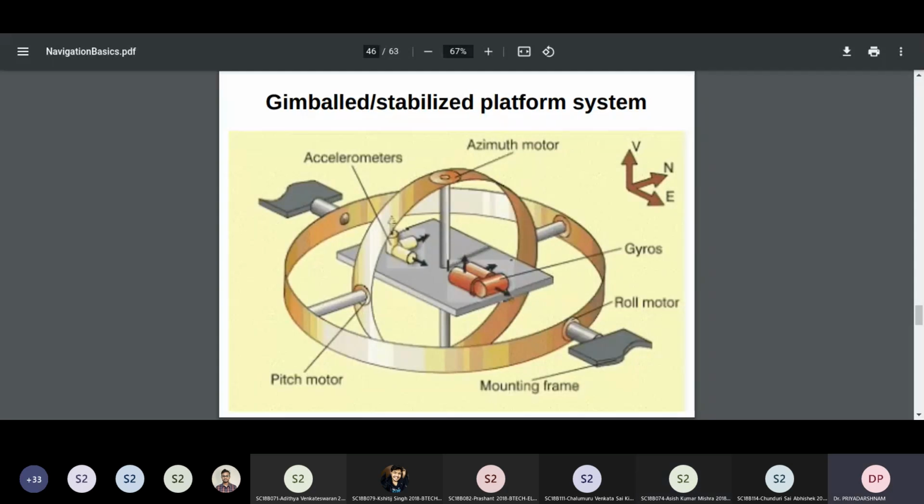You have to carefully calibrate this during the initial test itself. On the ground itself, these calibrations are made to make sure that you are able to quickly compensate for that. The friction coefficient has to be computed. So these inner gyroscopes are precisely doing that. And you need very sensitive inner gyroscopes. Even the smallest moment has to be measured. But one advantage is the gyroscopes need not have wide dynamic range. It is only friction compensation that it has to do.